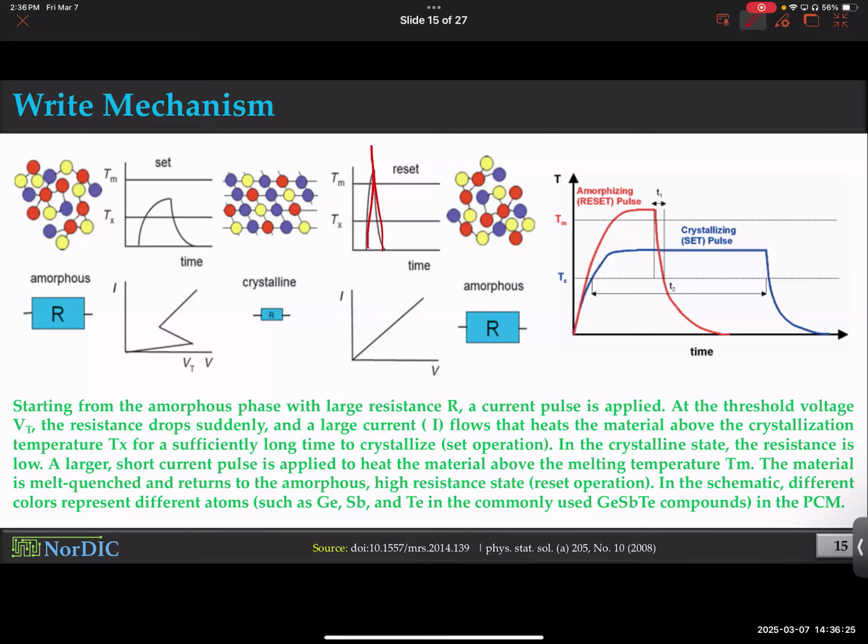The first approach, when we are going from amorphous to crystalline, was not about melting. It's about just initiating the lattice redistribution. Exactly. But now it's all about melting and disrupting stuff. You have literally melted the material, but now you don't want to give it enough time to reorganize in a nice way. And that's what you get out of the material. You get amorphous.